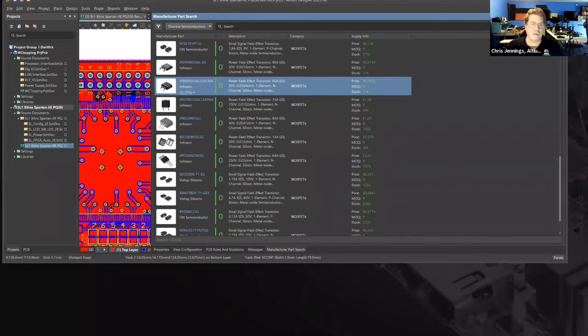Typically for me in a capacitor, it's the voltage level, it's the package size because we need it to still fit on the board, and it's the capacitance value, right? So voltage, capacitance value, and footprint, or basically the body. And quite often there's a lot of options, but that's one of the things that I've seen quite often too.